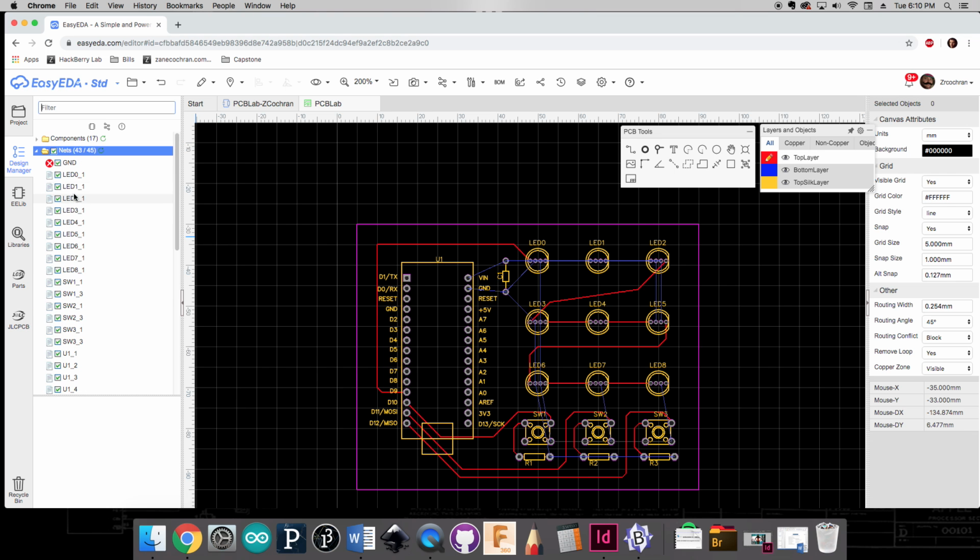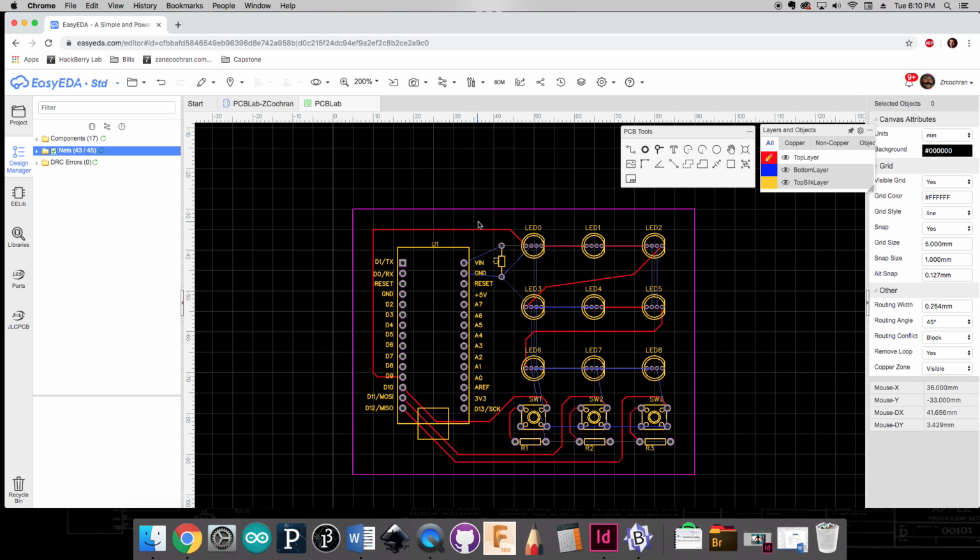Okay. So we just had to click refresh, and you can see that the only nets that aren't set up now are the ground and the power. Good. Okay, so that's where we want to be. So now what we can do is we're going to do what's called a ground plane. And the ground plane is going to create just a big giant piece of copper that's going to come through and actually connect all of the points that need to go to ground.